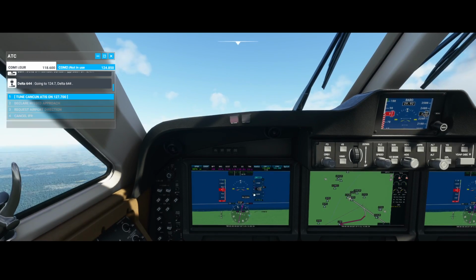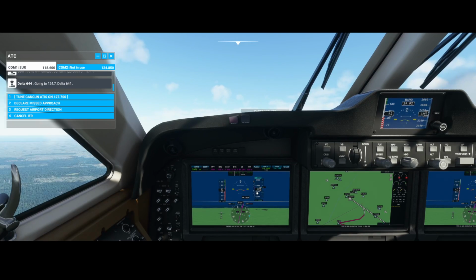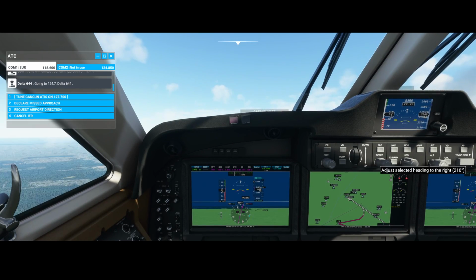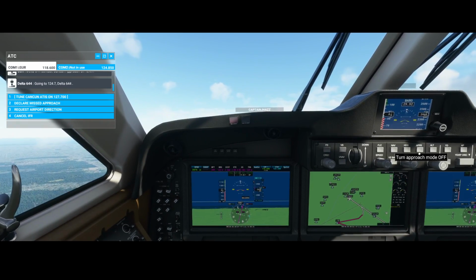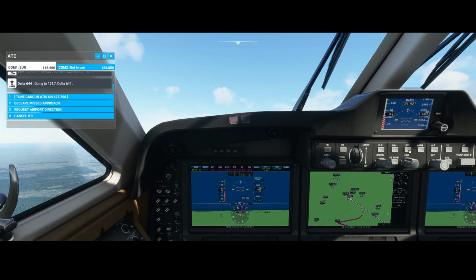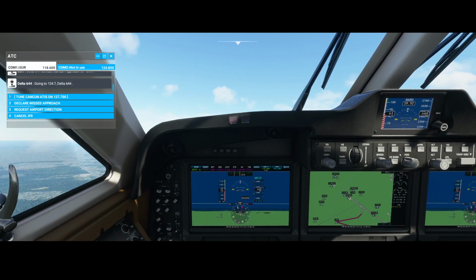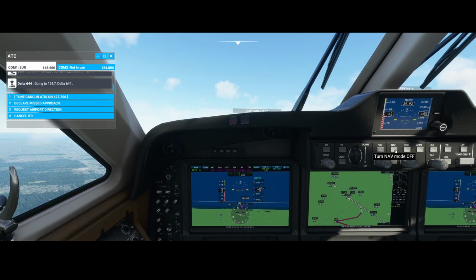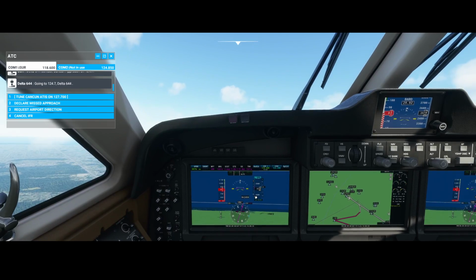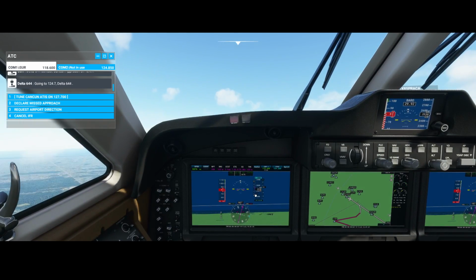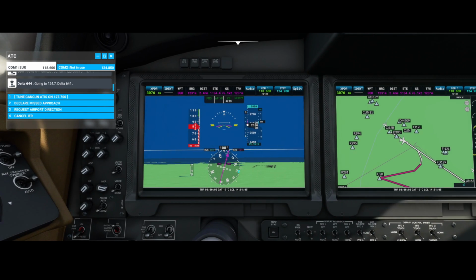Going to 124.7. Now what you see here is that ILS is being activated, right? So ILS is going active. So we're gonna press the approach button. And the approach button will normally... it was a little bit too fast, so let's use the nav mode for now. So what you will see is that once it's captured the ILS signal, it will go down and down, and at the end it will be somewhere in the center.